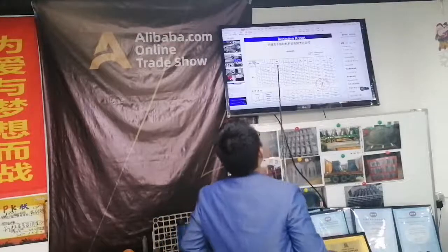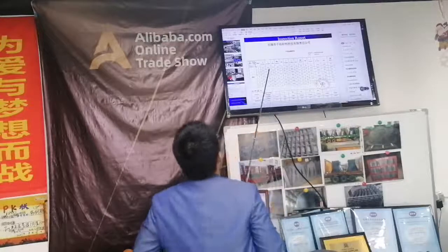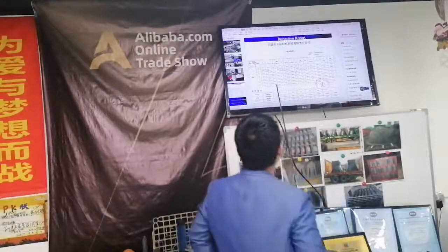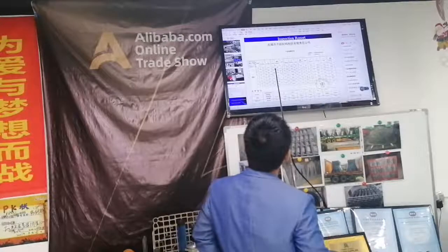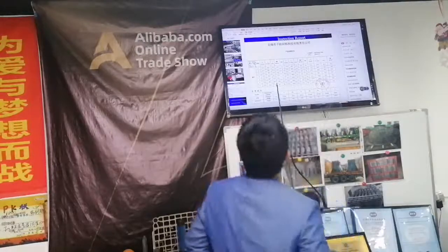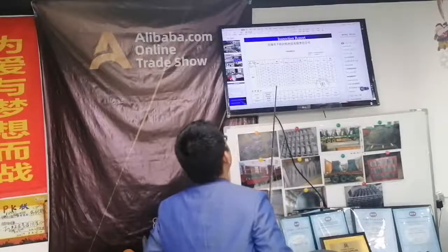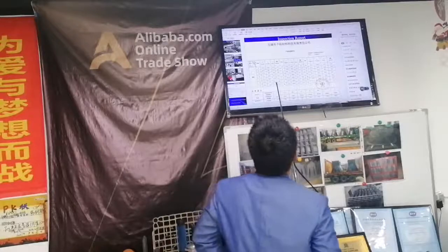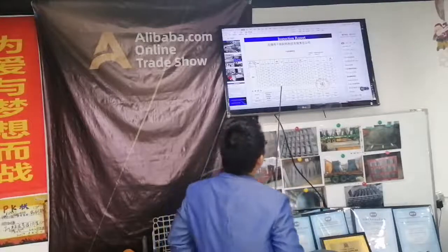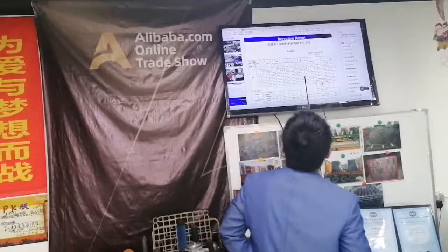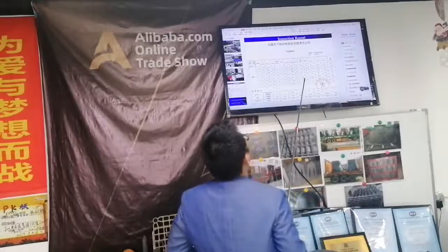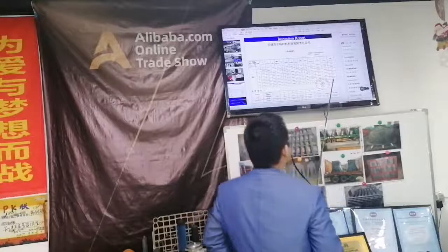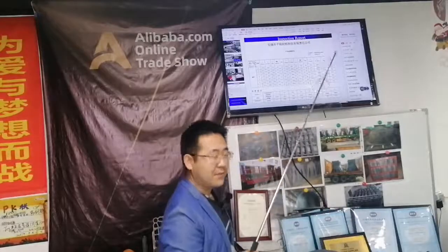This part, the hardness must be more than HRC 53, and our check set is HRC 56.2 and HRC 56.3 and HRC 60 and HRC 58.5 and HRC 54.